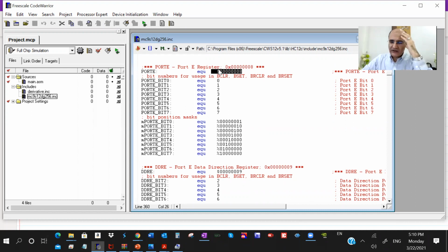And when we started talking about HCS12, these are registers. We said that registers here, the non-CPU registers. I'm not talking about the CPU registers, the accumulator, and the A, X, and Y index registers. We're talking about the other I/O and port registers.